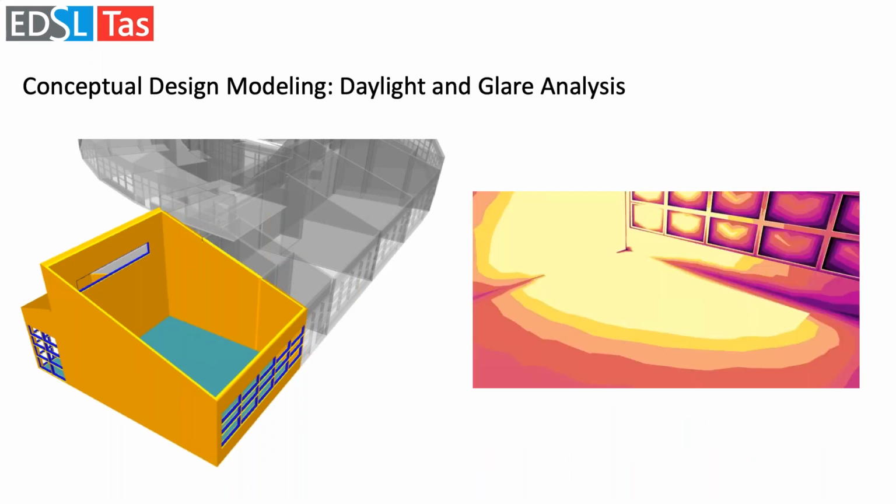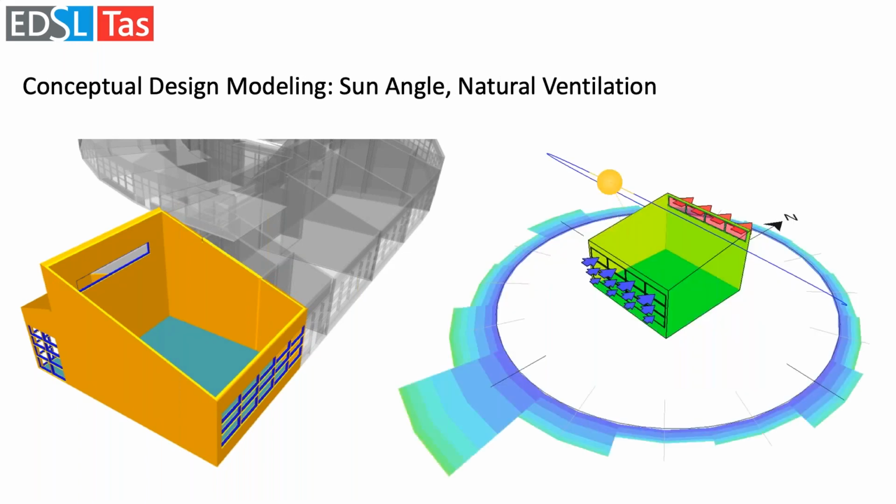So we have daylight being analyzed for this particular array of windows that have been applied. That could be changed back and forward as you iterate between the daylighting and maybe the impact of different window configurations, different operable windows, maybe having only the top row openable and things like that, just playing around with one room in a particular building, moving on from the one zone for a building in the simple box modeling type analysis.